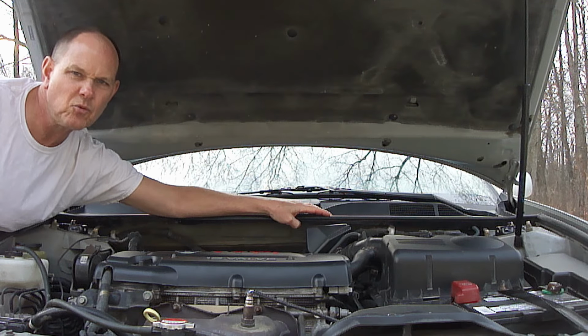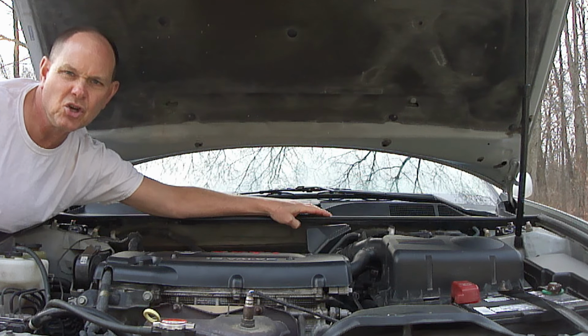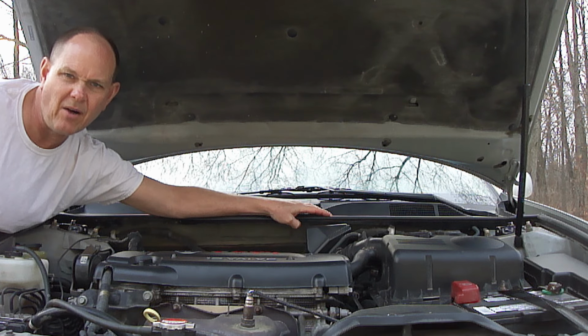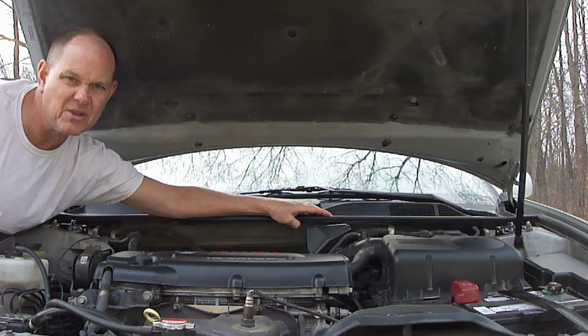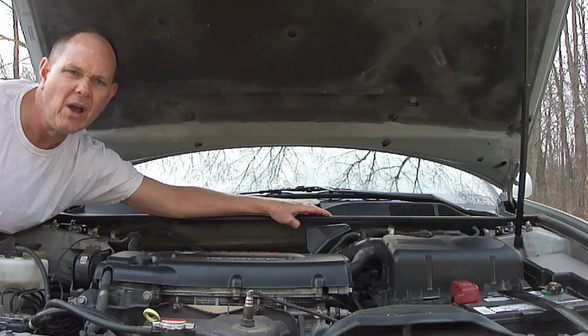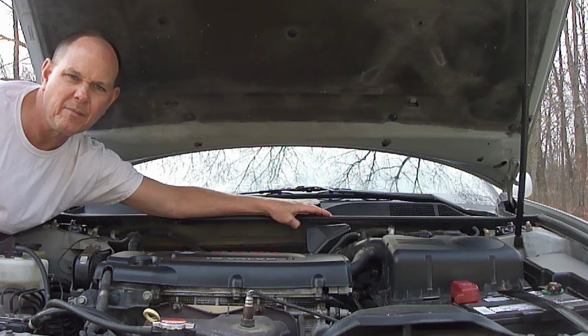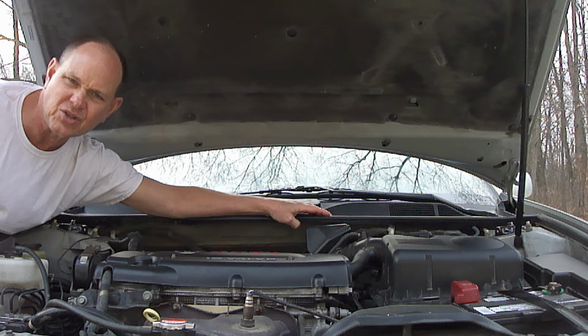If you do have to replace a pressure switch, make sure your system has a built-in check valve, which will prevent refrigerant from escaping once the switch is removed. Otherwise, the refrigerant will have to be removed prior to removing the pressure switch.